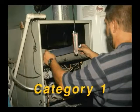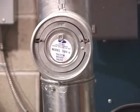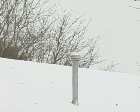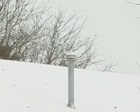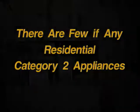So that covers the 4 ANSI categories of vented appliances. To review, Category 1 appliances include practically all traditional vented appliances that either have a draft hood or a barometric damper, as well as all mid-efficiency furnaces with inducer fans that are connected to conventional vertical chimneys where the draft in the vent is negative, caused by the heat of the rising gases. Residential Category 2 appliances don't currently exist, so we don't discuss them here.